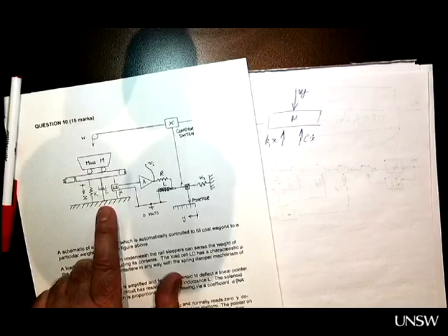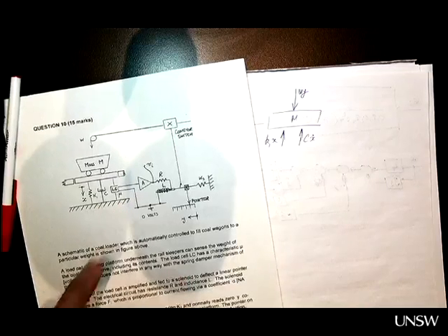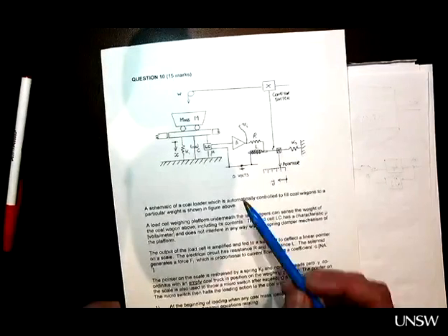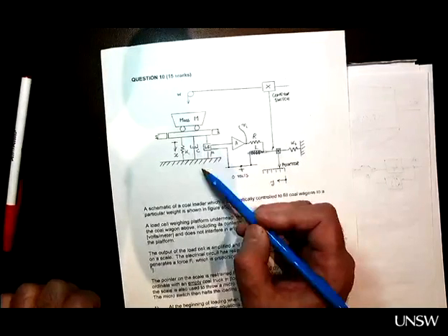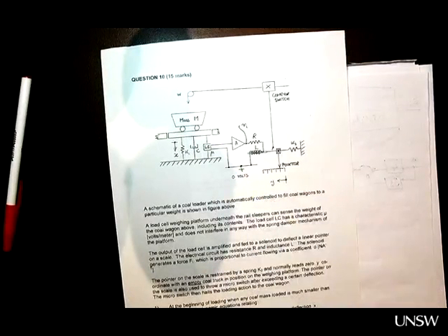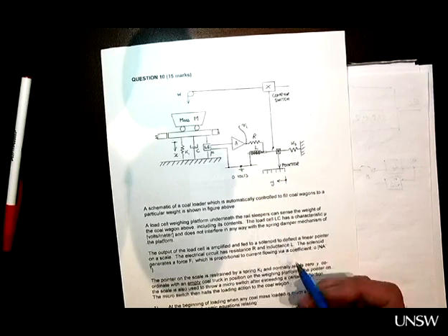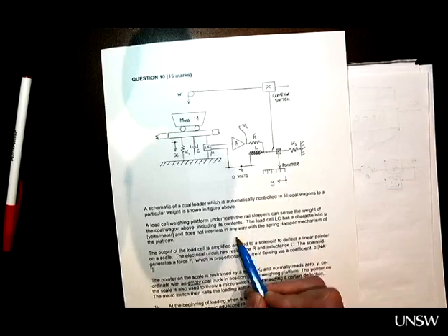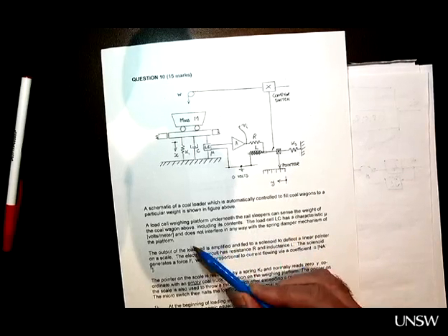If you check the text, the load cell has no effect on the movement of the platform. It's just there to sense the displacement, but doesn't generate any forces to resist the movement of the platform. The load cell LC does not interfere in any way with the spring damper mechanism of the platform. So it's just sitting there and measuring displacement, not generating any forces.